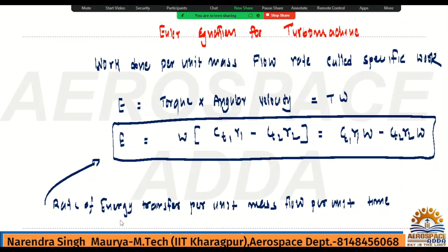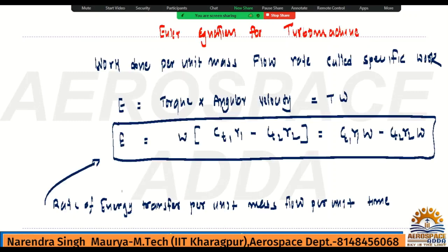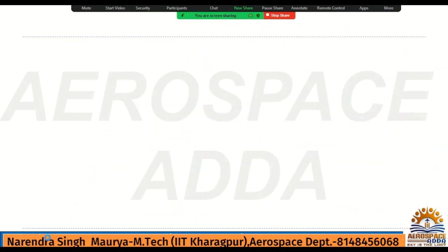So the same formula you can use, but if you write for the axial flow compressor, definitely the axial flow compressor inlet and exit diameter, or radius, will be the same, because it is an axial machine. Here the Euler equation of turbomachine I have given is a general formula, so there is an R1 and R2 you are getting. This formula you can mold according to your machine. If your machine is an axial machine, this diameter or radius will be the same at inlet and exit. Now because we have a compressor, we can write work input to the compressor.